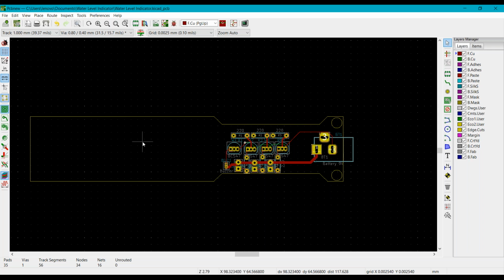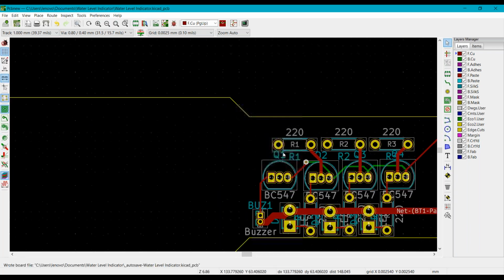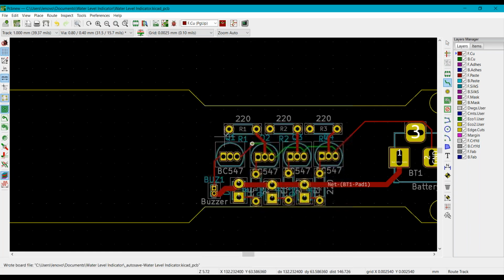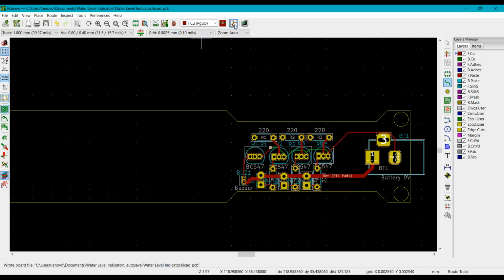If you remember our first session, we had discussed the ground planes. I told you, the ground plane should be as large as possible, and it should occupy every corner of the PCB except where there are signal lines. So the signal lines, one thing I had left, R1.